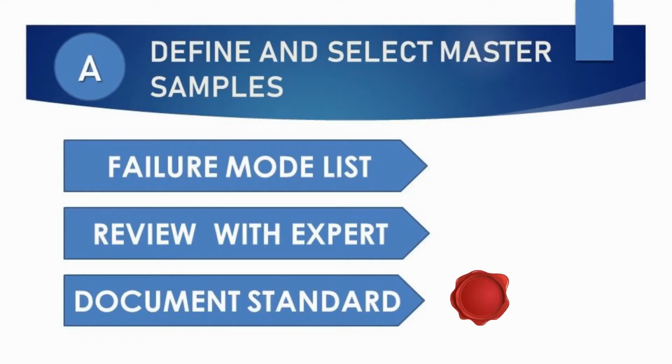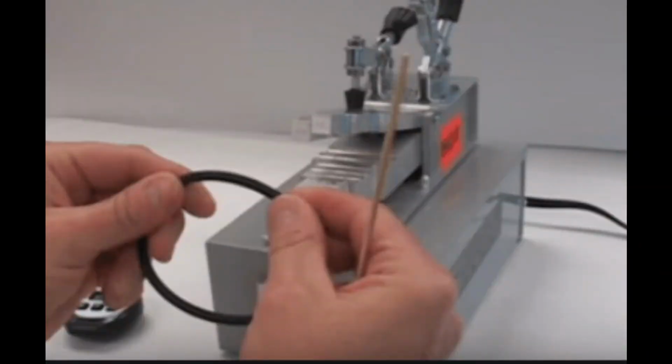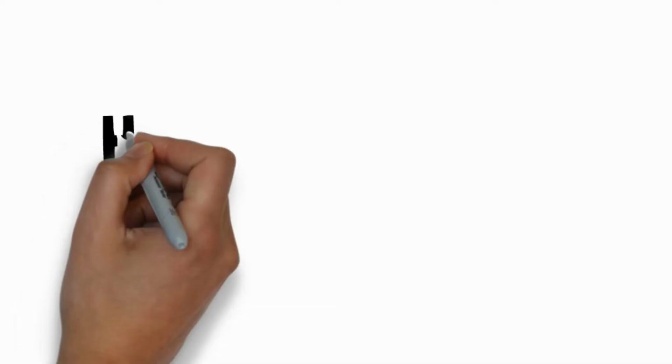And then we are going to document this standard, this list and classification that we get from the experts. There are some industries, like electronics, with the IPC. In the case of the O-rings, we are going to have burns, short shot, flash, deformation. And these standards define very clearly what is a defect and what is not a defect.